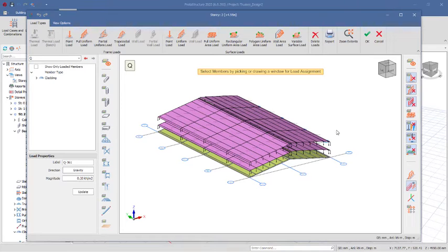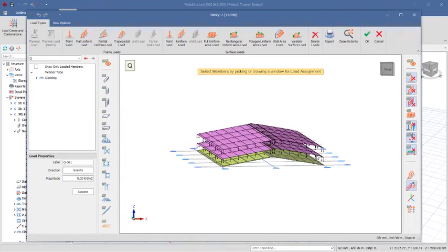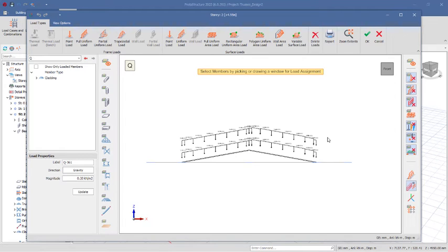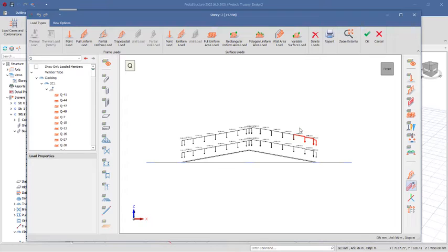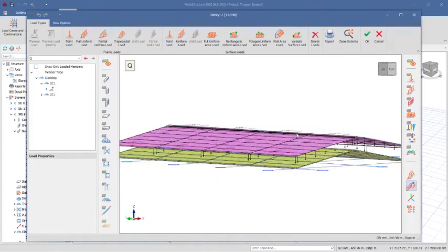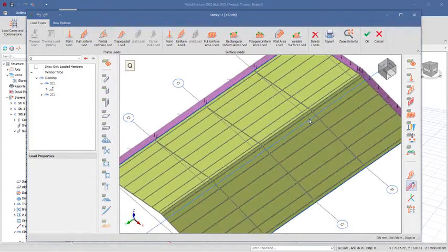You have also 2 layers loading. So go to the front. We are going to be removing the second layer. Okay, so select that, just like this. Hold the control key, continue to select. Make sure you do not select the second layer. Right, only the first layer we are removing. Right click and remove it, just like this. Go to the 3D. So we have our structure fully loaded